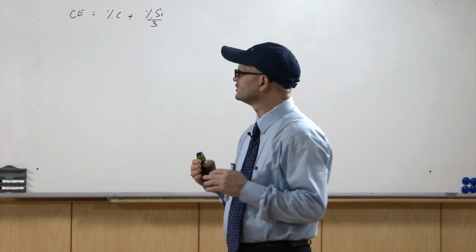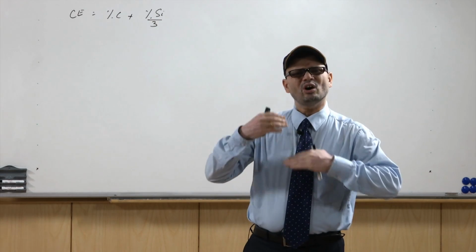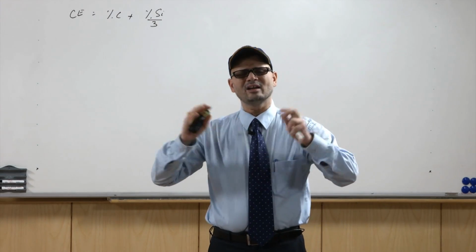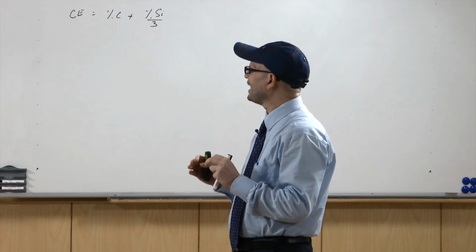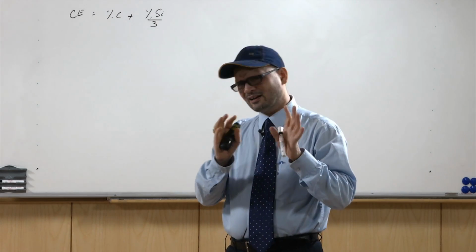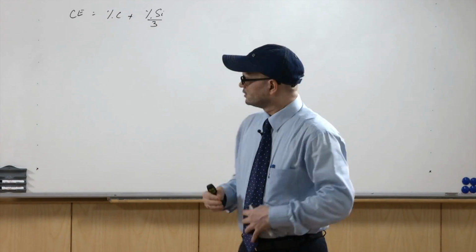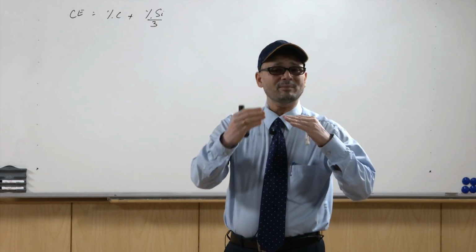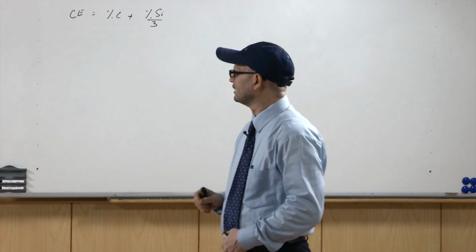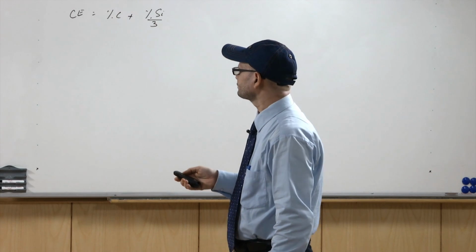So, in those cases you do not need the risers for that process, although a riser is required so that pressure is applied and you get a sound casting. But then you are not thinking much about the requirement of a riser for supplying extra metal because of volume requirements.